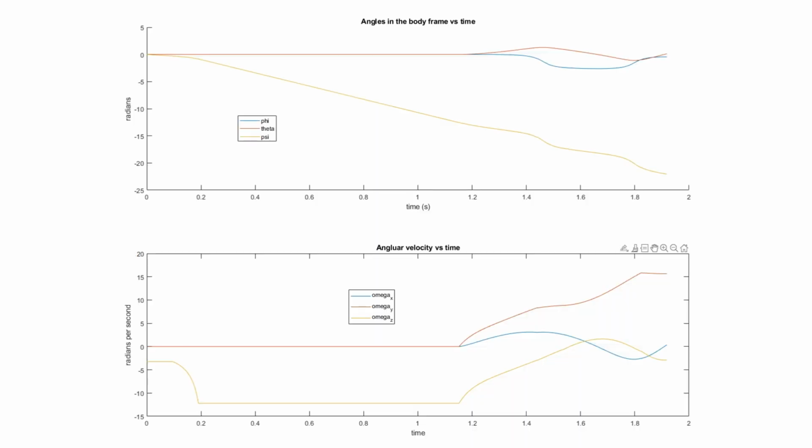After finishing our ODE45 simulation, we get back an array called y, which we can then index out to get back all of our important variables that the ODE45 function solved for, like phi, theta, psi, and all the omegas. Then we can plot that all onto separate graphs and see the continuous flows of our different information and how they all change throughout our time span.